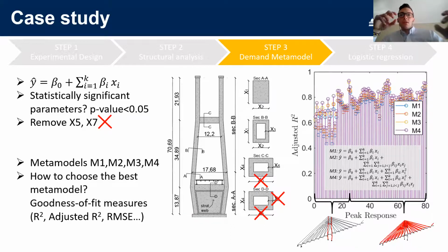Increasing the number of simulations from 80 to 160 improved the variability of the response, which suggested a higher prediction capacity of the Metamodels. When I ran the analysis only with the 18 starting time histories, the adjusted R-square was much lower than what you can observe here. And I think this can be higher, for example, if we consider a site-specific suite of ground motions.